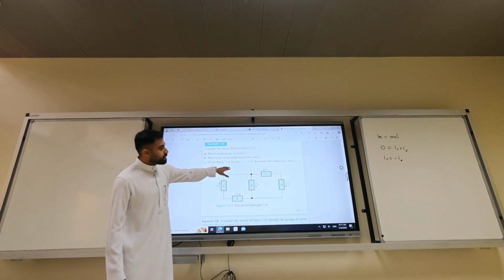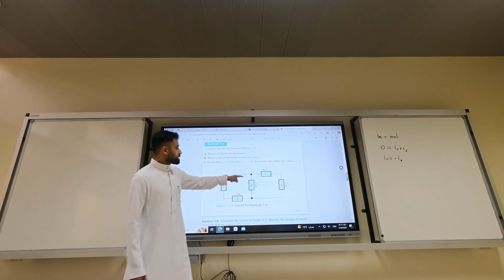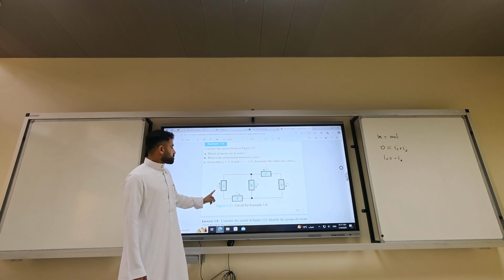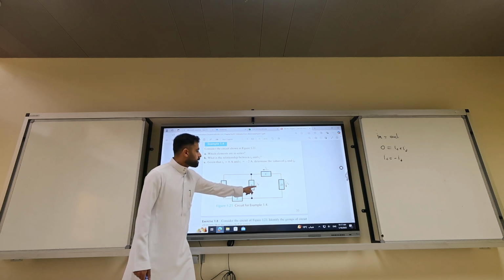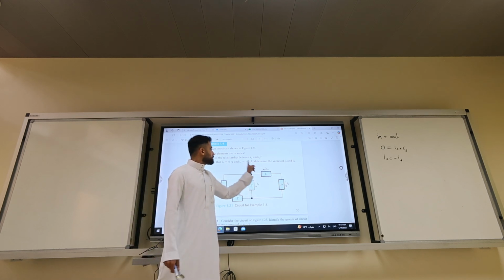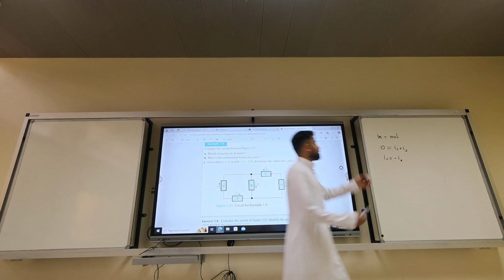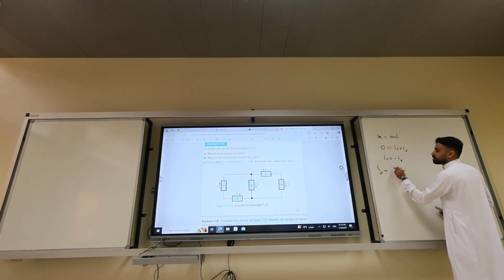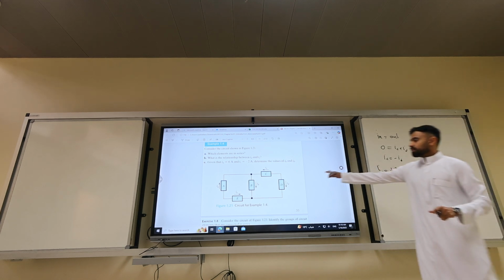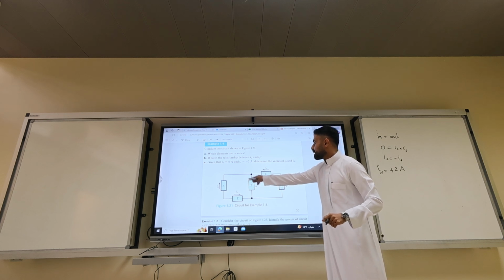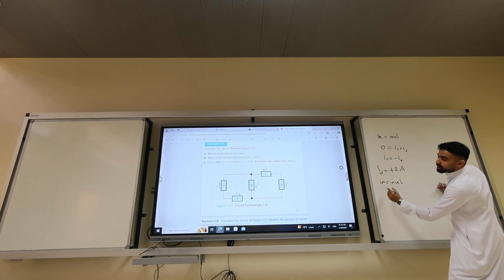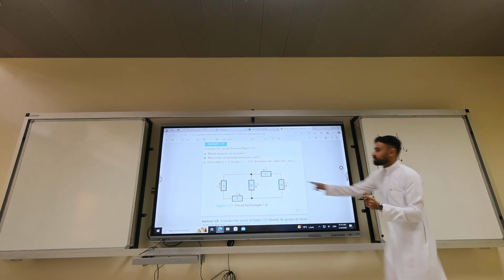Now, given that IA is 6 and IC is minus 2, determine the value of IB and ID. Well, we have an easy problem. We can calculate ID. ID is plus 2 from that relationship. So we have ID equal to plus 2. Okay, we don't care about ID. Now we have IC. So what is IB? In equal out. What is in? IA, 6, and this node.